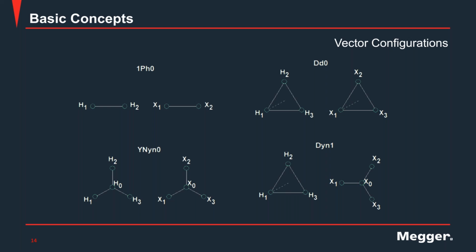So when I perform the test, and before we said I have to compare my measurements to my nameplate value to know if my results are within the accepted limits. When I have a three-phase transformer, I need to consider a correction factor. It's not a direct ratio as I showed you before, just dividing my primary by the secondary rated voltages. I need a correction factor, and that correction factor will depend on the configuration of my windings, the connection I have for the windings I'm testing.